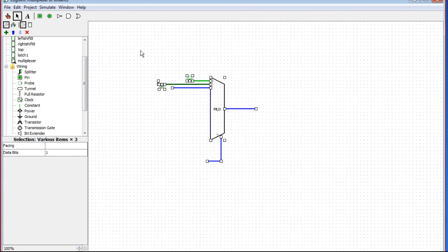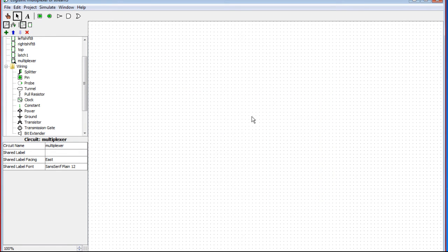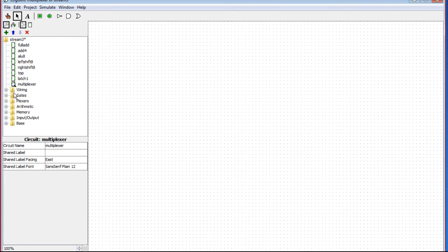And the reason I'm saying this is because that is how FPGAs work, I think. I believe, at least when I was in university, that's how they worked, and I don't think they've changed. So you have a whole big array of multiplexers, and these inputs are all connected to SRAM blocks. Every SRAM is configurable, so you can configure the function of every multiplexer, and you can configure the interconnections between multiplexers, and that is how you synthesize any kind of digital circuit in an FPGA. Not important for what we're doing here, just some trivia.